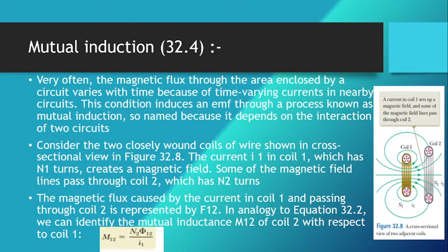We can say that M is the link or the sensitivity between the two coils, and it is the induced EMF in the secondary coil due to a change in the current in the primary coil by 1 ampere in 1 second. M is also affected by some factors, which are the distance between the two coils, number of turns, volume of the coil, and core permeability, and we will discuss them now.